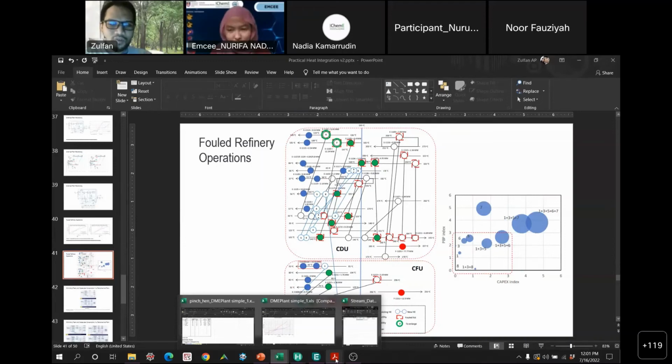If the assumed U value is the same as the calculated U value, you get a converged U value, which you then put in the process data sheet. That U value is what we call the design U value. So we compare that design U value with the calculated U value in the field, because in the field, you know the flow rate based on the mass balance. If there is a flow meter, that's good.